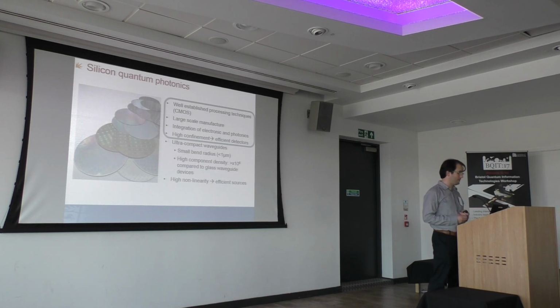Finally, we have maybe the possibility of integration of electronics and photonics. So we may have some detectors, and then we're hopefully thinking about integrating electronics along with these. And finally, we have high confinement, and this leads to efficient detectors. So all of our detectors are really evanescently coupled detectors, as we'll see. Okay, so this was the very quick and broad overview of why I might care about an integrated